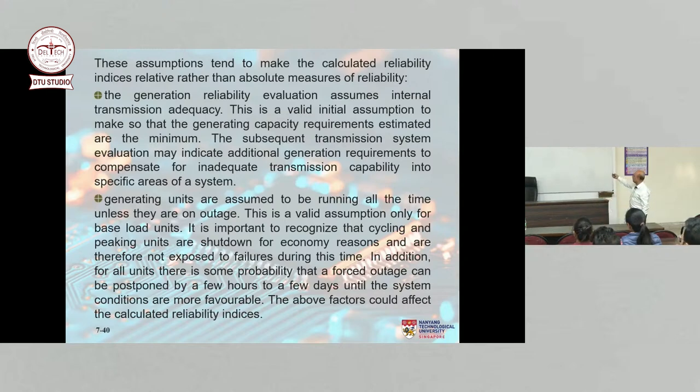Generating units are assumed to be running all the time unless they are on outage. May or may not be true. Yes, base load generators are almost always running, but not peak shaving units. So therefore, we have to look at this in an operational manner also, which in this course we have not done. We have only looked at long-term planning, adequacy. That's why we call it adequacy.